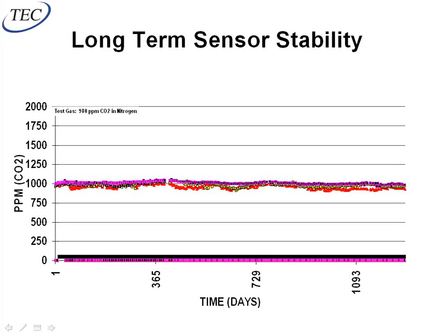And when there's less people in the space and less breathing, I'm going to throttle back from the 30% down to 20, 15, whatever it needs to be. Right? So I'm going to modulate down, not up. I'm never going to bring in more than the code required outside air. I'm never going to bring in more than the code required ventilation rate to the VAV zone. So hopefully that makes sense.